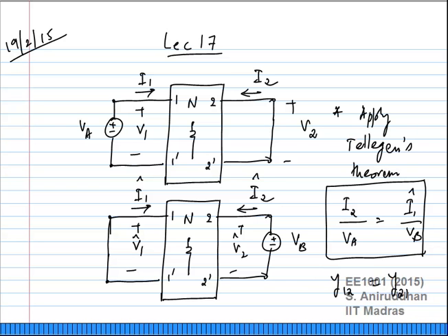In the simplest case, for example, if you were applying a voltage and looking at the current, you can represent it in terms of the Y parameters. Y21 will be equal to Y12. You can get different relations between the other 2-port parameters also.